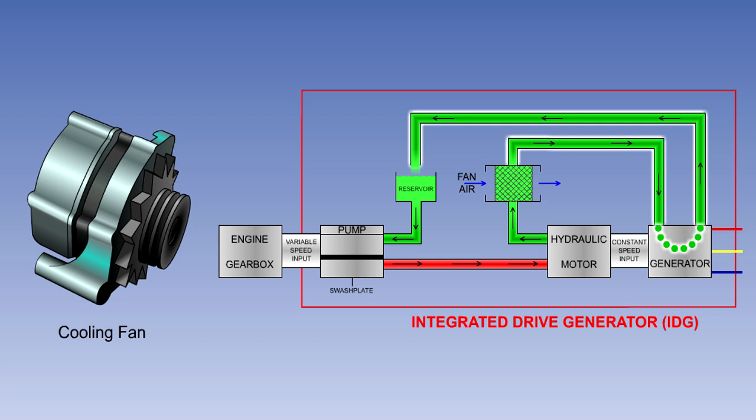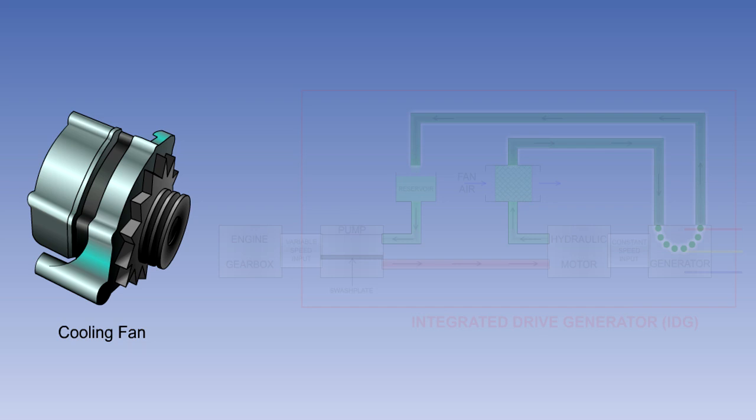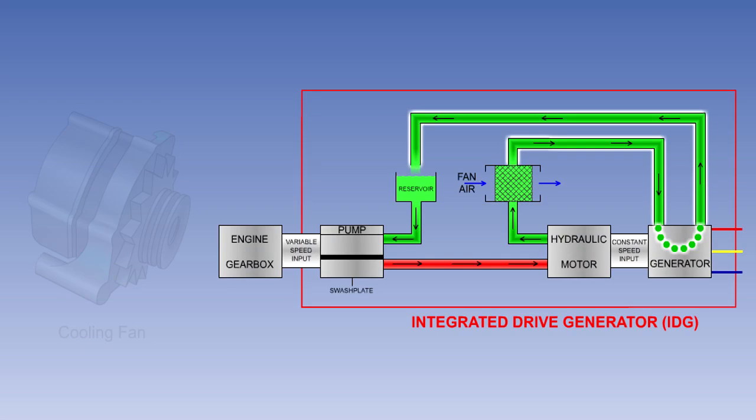There is a great deal of heat generated in a generator's stator windings due to the current flow through them, and some form of cooling system is required. Frequency wild generators or constant frequency generators with separate constant speed drive units typically use ram air cooling in flight and some means, such as a mechanical impeller, to induce airflow on the ground. Integrated drive generators use the oil from the speed control system to cool the stators. The oil is cooled in its own oil cooler.